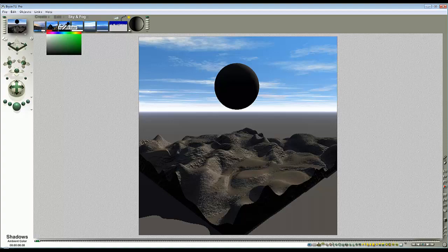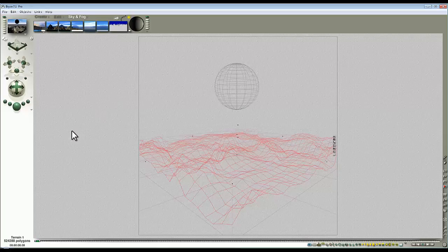So I'm going to set the ambient colour to fully black and modify the material so it has no ambient output and give it 100 diffuse. If we're going to use more sophisticated lighting models, then you don't really want any ambient response in a material unless that material is providing a special effect, unless you want it to glow. So if you do want something that looks like it's glowing, you can use ambient to create that effect. It's not the only way, but it is an effective way. So I'll just check out of that now. We've eliminated ambient from our scene, and I've turned the global ambient to fully black, so that's belts and braces.